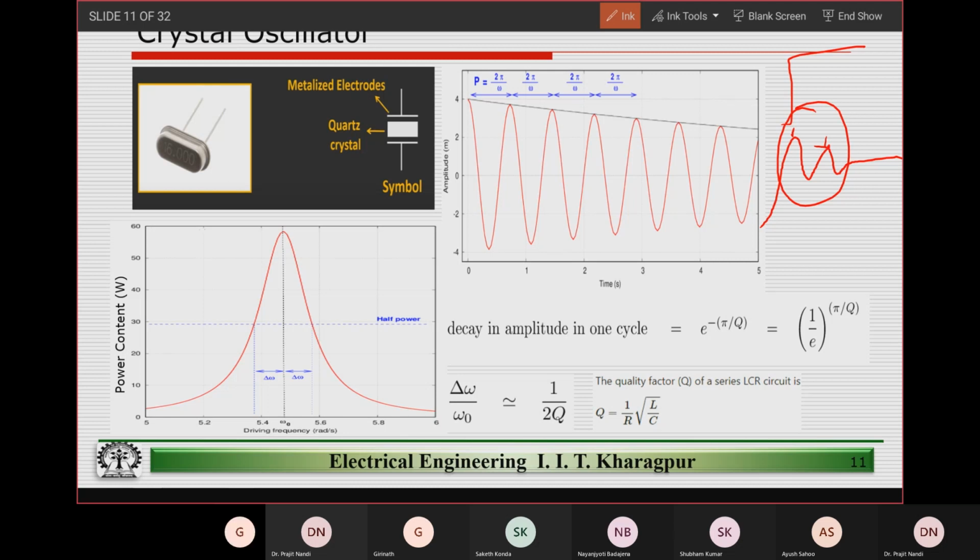When I design an amplifier, the first thing I do is to ensure that all the DC biasing of the transistors and everything is fine. And even before I run a stability analysis, I will probably just give an input step and see how the time domain is looking. That gives me a quick feeling of where my stability is. So when I'm looking at a phase margin, I don't have to go to another test bench or test setup to do the AC analysis.